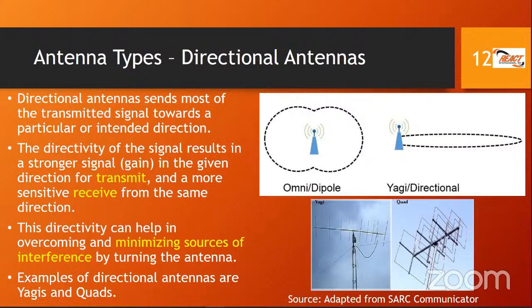They do put copper radials, copper wire, on the ground or in the ground to get better transmission, a lower noise floor and that sort of thing. So hams who can afford it will put several radials. It's not as though you slope radials for HF, and typically the antennas with the sloping radials don't go on the ground in any event.